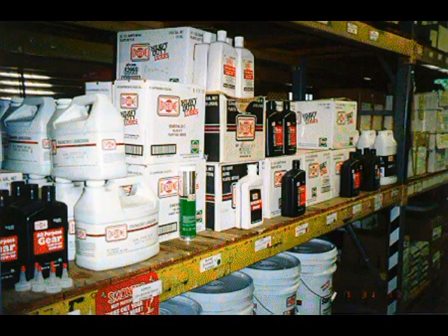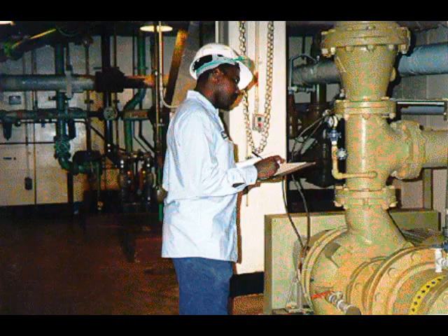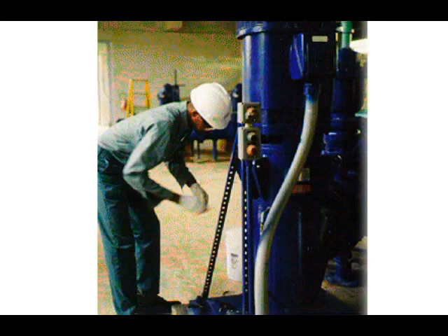Oils and greases must not be mixed, since the additives of different oils, when combined, can cause a breakdown of the lubricant. A helpful visual tool to organize lubricants and avoid mixing different types is to assign each lubrication point a color code by type of lubricant. It is also helpful to keep a log of lubrication and other maintenance performed. The motor manufacturer can provide guidance on preventive maintenance procedures.